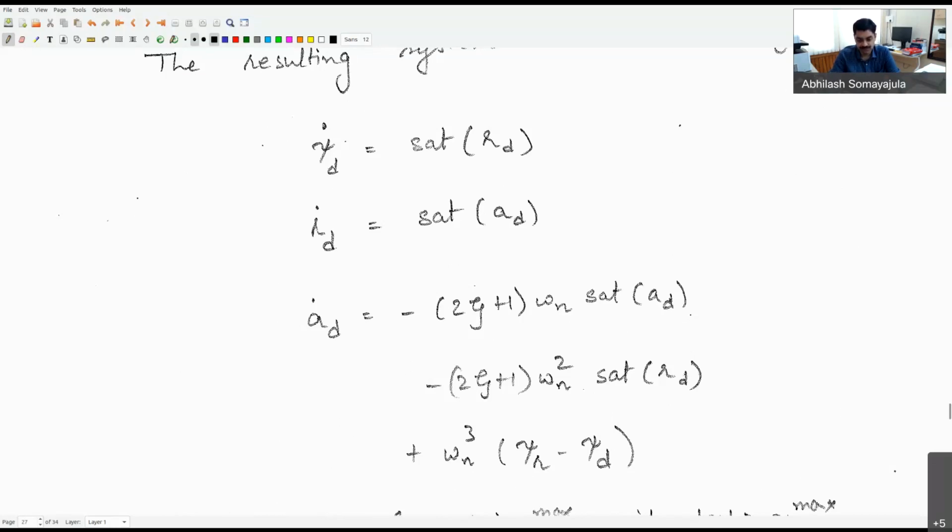Here we are simply basing the idea that the reference value being provided is getting converted into the so-called desired yaw trajectories. We are here only looking at the yaw trajectories using this so-called third order filter, which we have chosen as our guidance system. The main idea behind using these filters is that they are relatively simple to program and they are not complex in terms of the computation effort which is required. So they can easily be implemented on any vehicle.